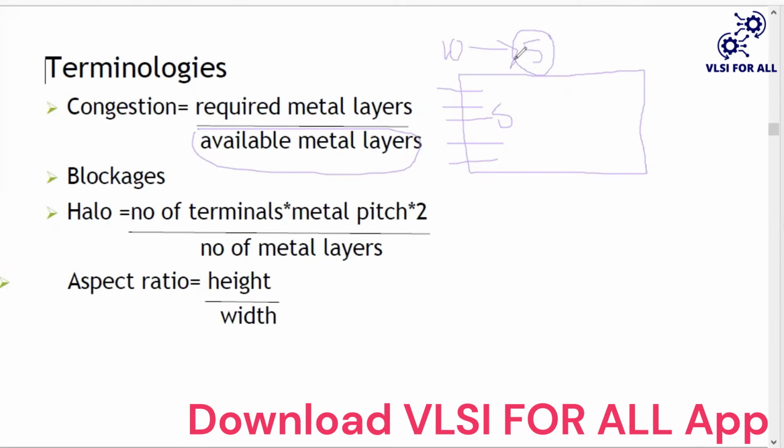Okay, we can fix the congestion, but we can cross verify the design input and output of the macros. There are multiple, 40 or 50 macros. Cross verify the connections of those macros. How many input connections and output connections are present, based on the fly lines? One concept is there: the fly lines concept. Based on the fly lines concept, we can place our design macros.